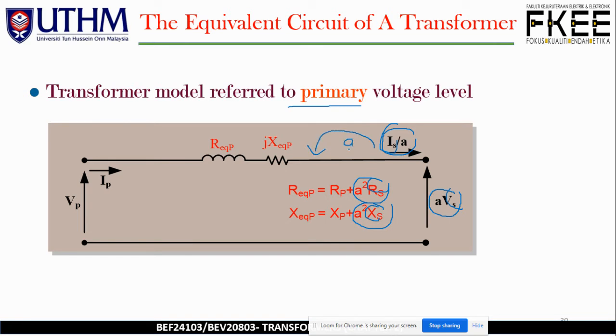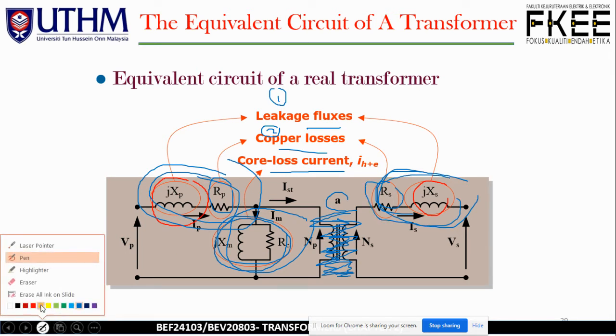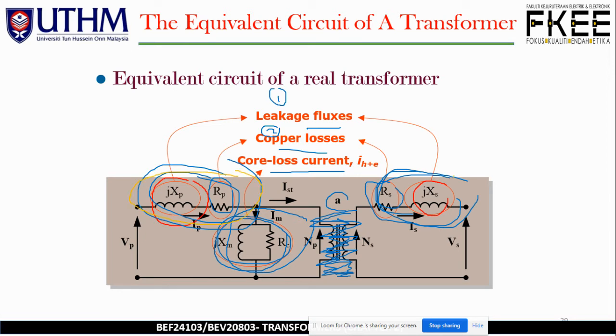Just imagine this is your a with the coil over here. Now we have shifted over to the primary, and we have changed the elements IS, VS, RS, and XS, and it now comes in series. Everything is in series, this part and this part, the one I colored in, let's say, yellow.